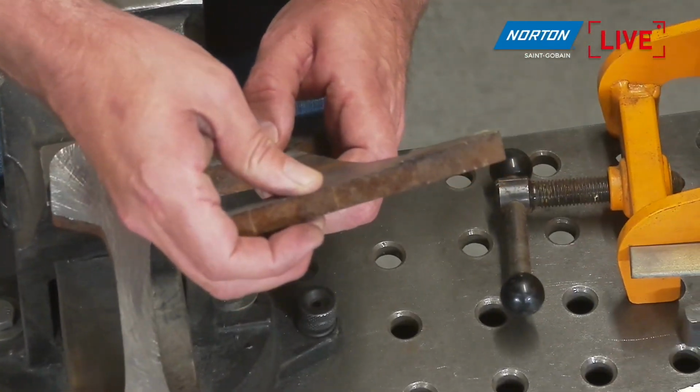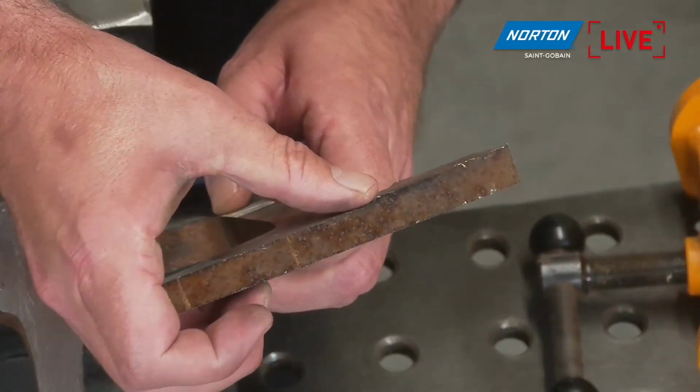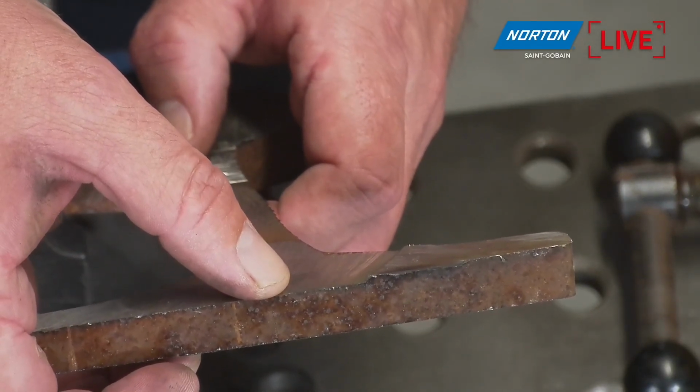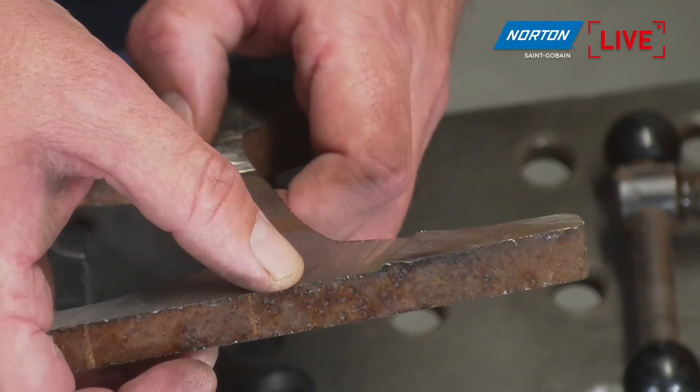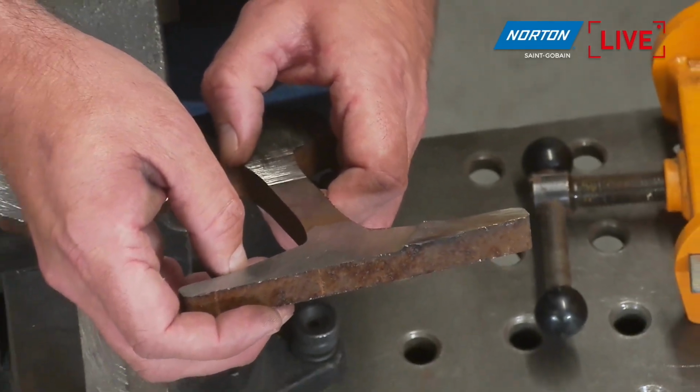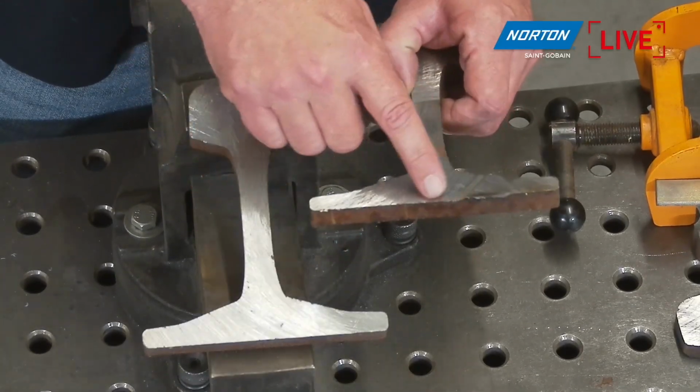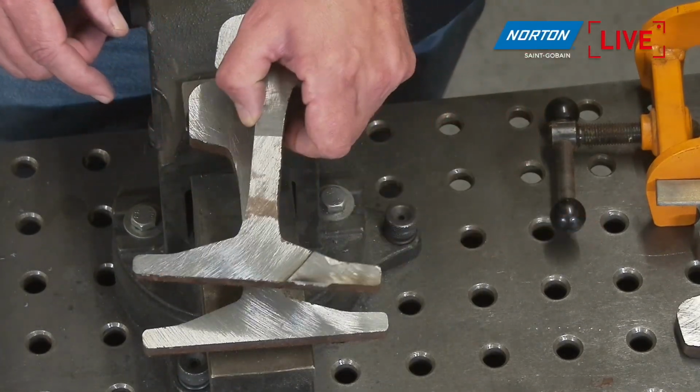How can you get to that? There we go. We have a step here where that blade has not cut straight when we've gone through from the other side. That's a problem. Okay. When we go to weld that, it's gonna cause us some issues. We also see a lot of burrs on here as well. So yeah, not ideal. So yeah, important to get the cut right and get it right first time. Again, we're saving time by doing that, saving rework.